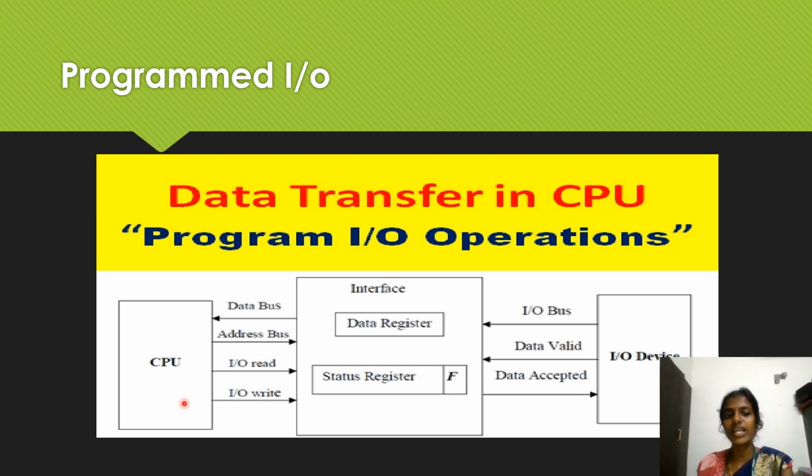The CPU is going to be waiting until my status register is set to 1, that is, until my data register has a value. If the particular value is present, it will be set to 1. Until then, this particular CPU will be waiting. So this is one disadvantage in my programmed IO. To overcome this disadvantage, we go for the interrupt-driven IO, which we will see in the next class.